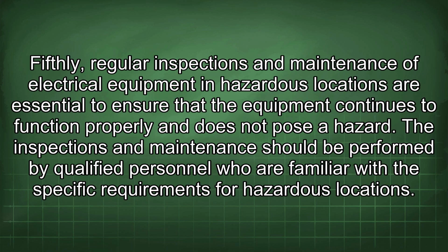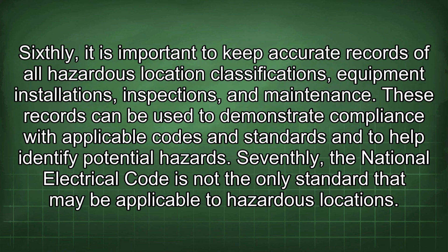Fifthly, regular inspections and maintenance of electrical equipment in hazardous locations are essential to ensure that the equipment continues to function properly and does not pose a hazard. The inspections and maintenance should be performed by qualified personnel who are familiar with the specific requirements for hazardous locations. Sixthly, it is important to keep accurate records of all hazardous location classifications, equipment installations, inspections, and maintenance. These records can be used to demonstrate compliance with applicable codes and standards and to help identify potential hazards.